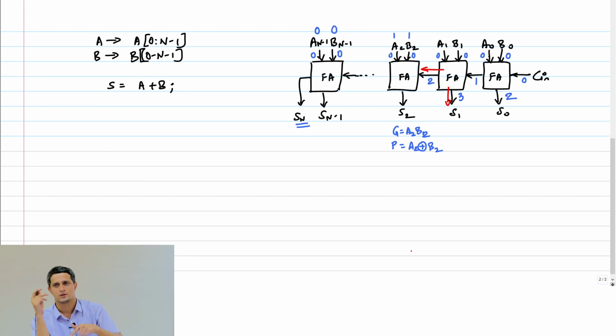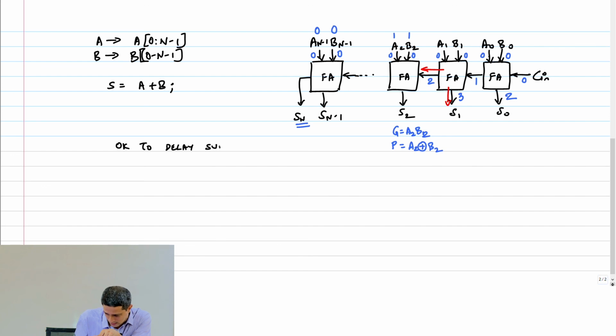Right? So I'm saying it's sort of a deadlock argument. Unless I tell you why I gave you this 1 and 2, you cannot argue this critical path correctly. So I'm just trying to resolve that deadlock. The carry is more important than the sum because that is propagating, sum is not propagating, and therefore it's okay to delay the sum in general. Okay, so it is okay to delay sum generation.